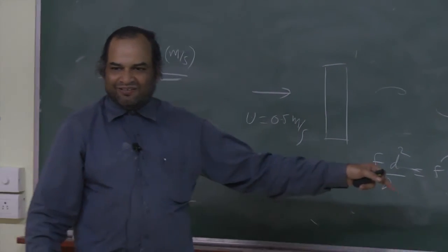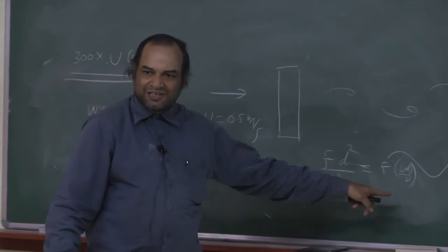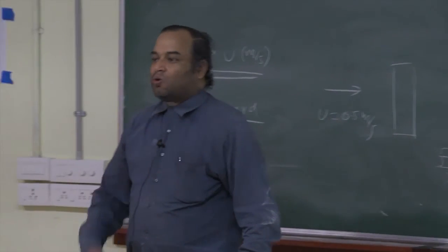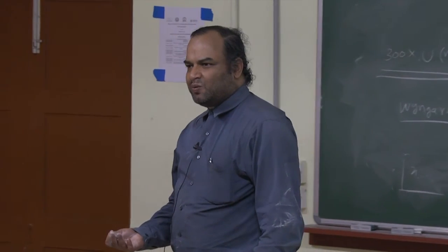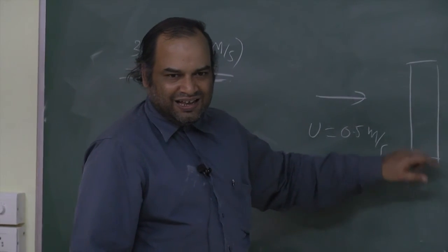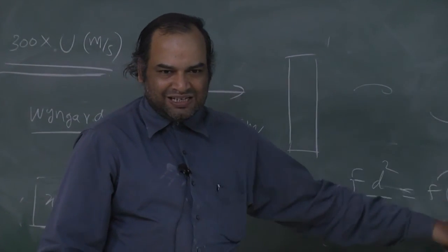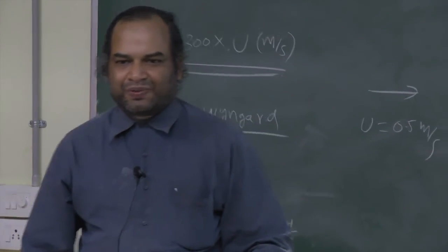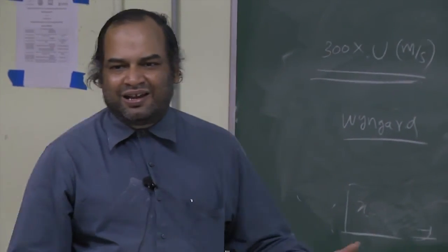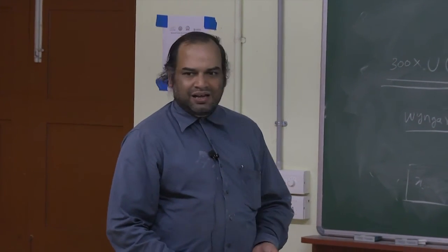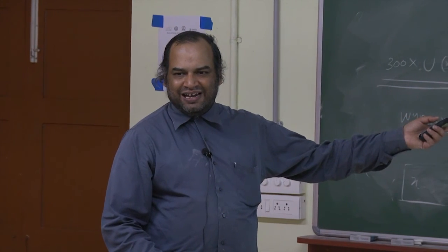Very well known, okay. So by measuring the frequency, you can immediately find the Reynolds number and the velocity. That's how you could use it. If you want to measure very low velocities successfully using a hot wire, use what is known as a vortex meter. This is just a cylinder with vortex shedding behind it; put the hot wire here, get its frequency, and from there you can use a correlation to get the velocity. Okay, that's just as an aside.